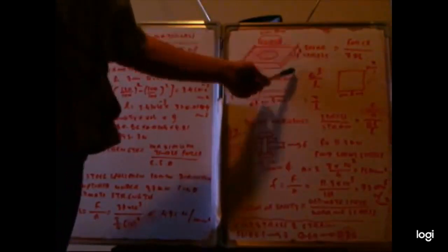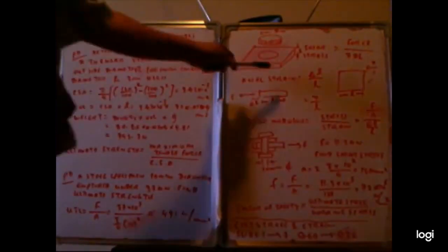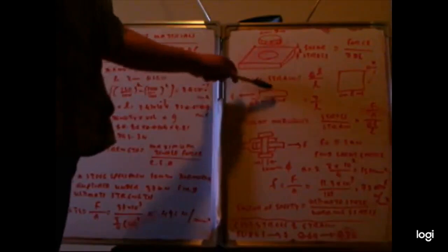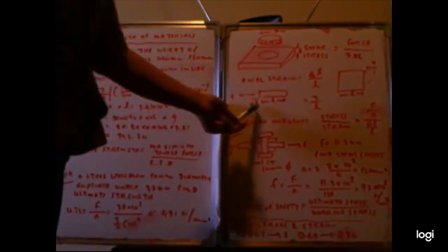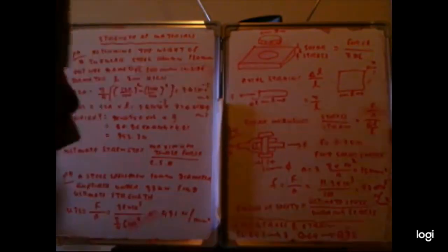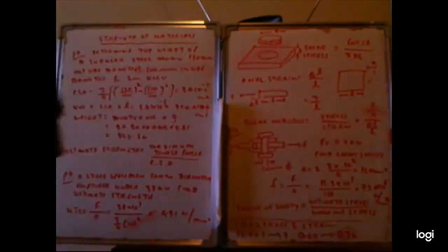Shear strength means that this is the perpendicular force. So this perpendicular force is punched at this metal. So the shear strength can be calculated: force by pi d t. Pi multiplied by this diameter and thickness. So strain is the deformation. When the force is applied, this part will elongate. So elongation is delta L, original length is L. So delta L by L is strain. And also the deformation, this is the deformation, original length L. So this is x by L.